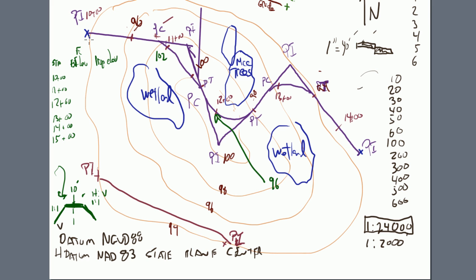So the steps. Have a topographic map, or some map at a standard engineering scale, hopefully. Standard engineering scale can be read on a standard engineering scale. Know your datum, know your coordinate systems. Put in your horizontal constraints, what you need to keep and lose. Draft straight tangents. Put in your curves, guessing if nothing else. And that's what the highway survey class is about.